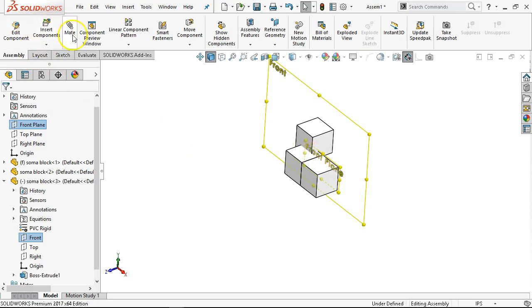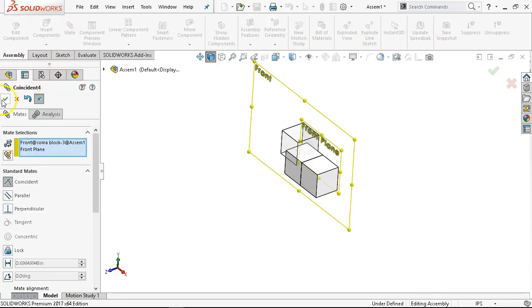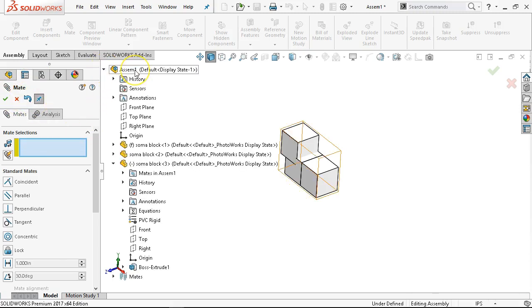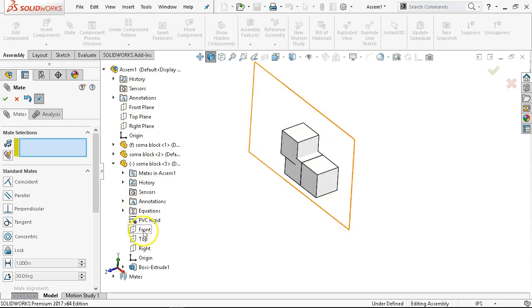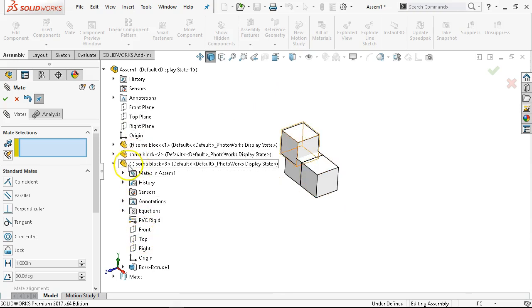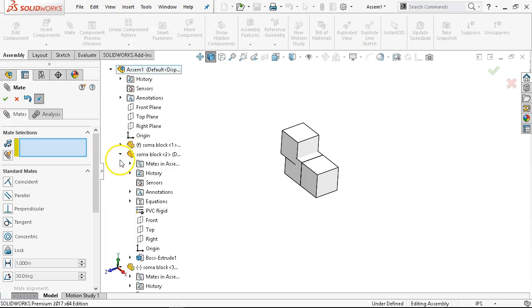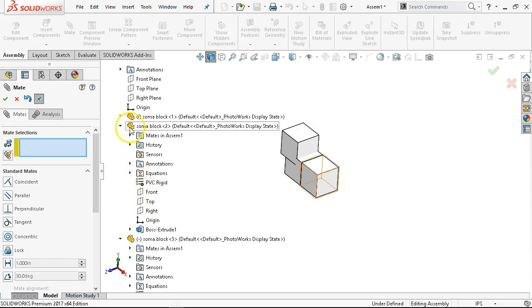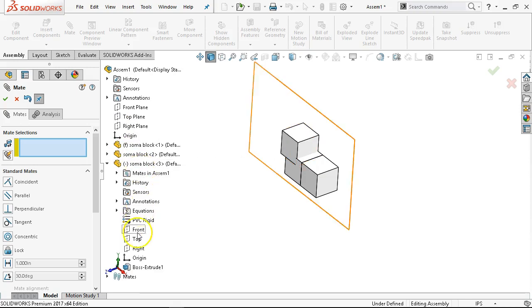All right, so we'll go to the main. That brings it up coincident. And we need to expand out the flyout. The flyout gives you access to that geometry. In here I want to make sure I'm in the very last one, the one with the minus, because it's easy to have two or three of these expanded. I'm picking this one, but no, that one's already defined. So we need to watch where we're making that selection.